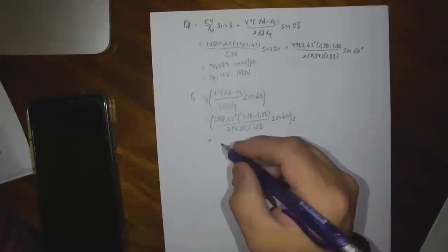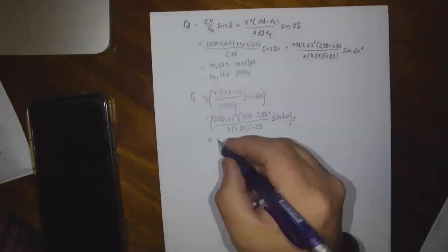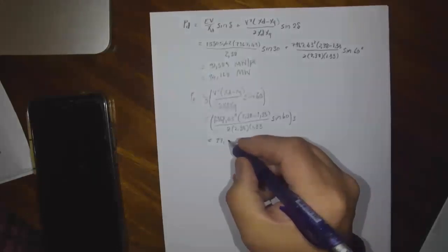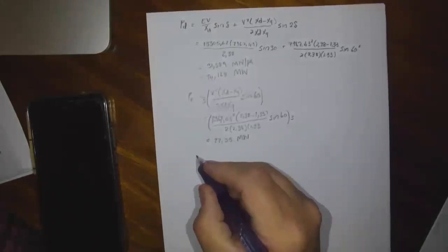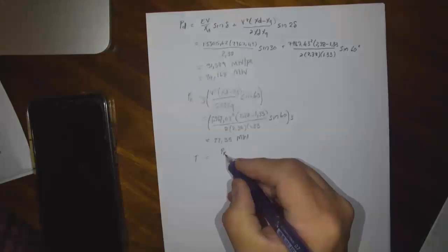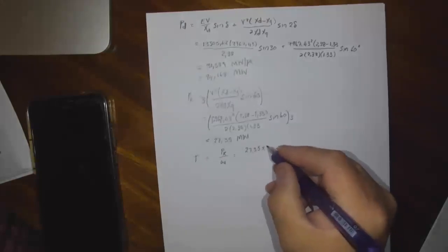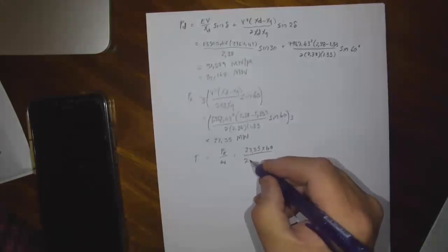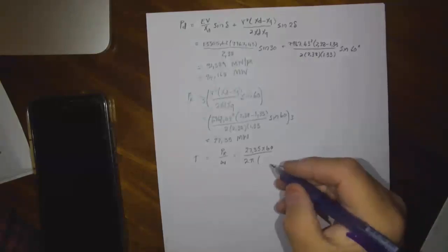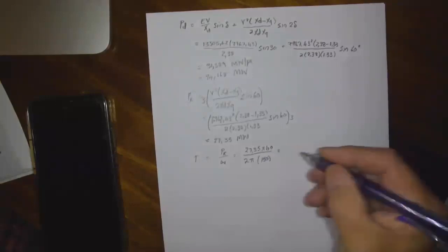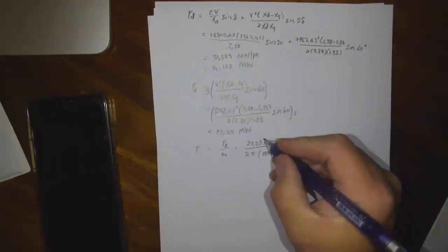27.354 megawatt, after you've multiplied it by 3. Right. So now torque is going to be P reluctance over omega. So that is 27.35 times 60 over 2 pi, and it's a 40 pole, so it's 3,000 divided by 20, which is 150 rpm. Yeah? And then you should get your 1.74 meganewton.